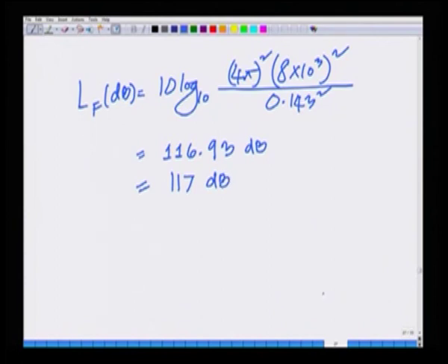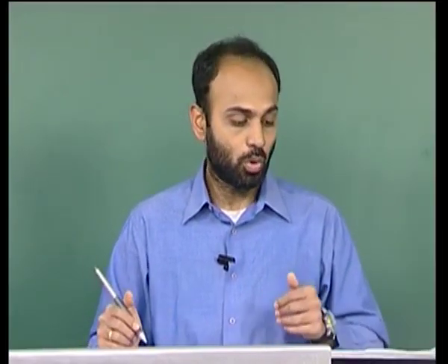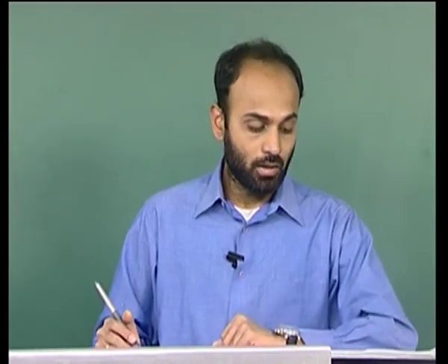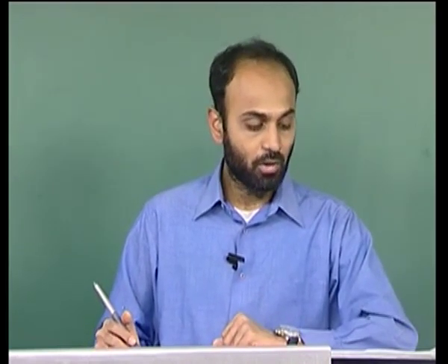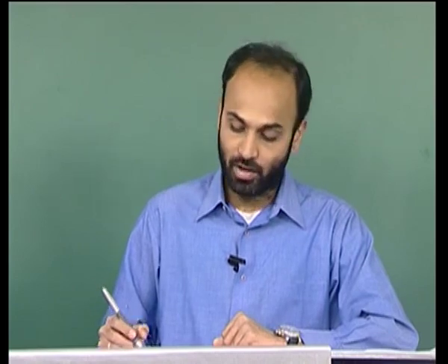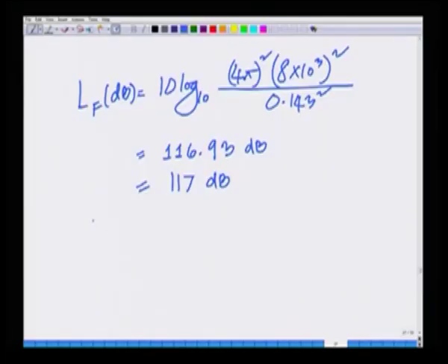All right. So, that is the free space path loss if there are no obstructions. This is what the path loss would be, but obviously in a city environment we would have a lot of obstructions leading to scattering and reflection. So, what would the additional factors be? First, we have to look at the transmit antenna height gain factor, that is HTE.